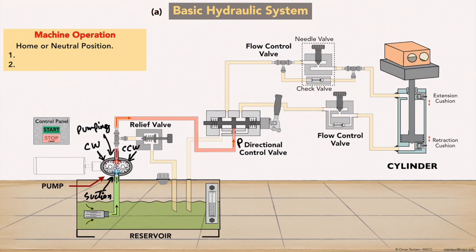Inside this valve are 2 piston rod units, one on each side, and 1 piston double rod unit in the middle. So totally we have 3 piston rod units, meaning 3 positions the cylinder can have. The 3 units are attached together as a single component called a plunger. Shifting the plunger all the way to the left or all the way to the right is done by moving the handle forward or backward.